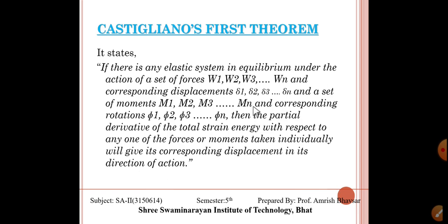And a set of moments, whenever we apply moments on the elastic body, that is M1, M2, M3 up to Mn, and the corresponding rotations induced in our elastic body, that is phi 1, phi 2, phi 3 up to phi n, the partial derivative of the total strain energy due to these moments and loads, with respect to any one force or any one moment taken individually, will give us the corresponding displacement in the direction of action.